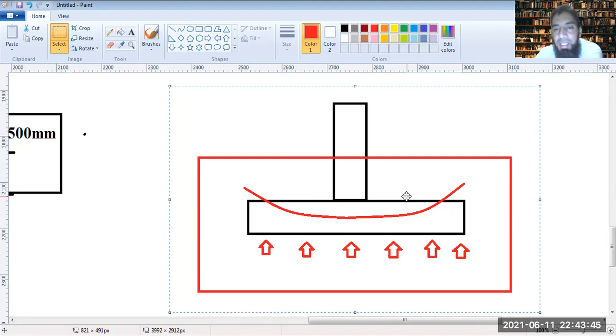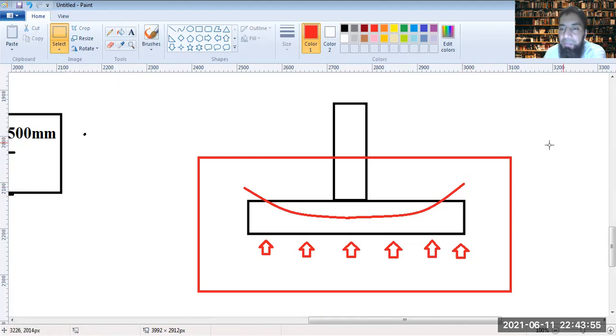Now this is a similar case to a slab design, but in slabs you actually have the supports towards the ends, and then the hogging is happening. Here there is no support towards the ends, but the support is at the center. If I reverse this system, then what we have got from the distribution of the base pressure is the area that is now required.